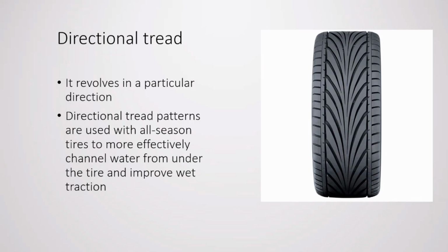Then we can experience more vibrations and jerking, because the tread pattern is designed based on the rotational direction. Especially, it will lose traction once we have some sort of wet condition. If there are wet conditions, then the traction will be drastically reduced, right? So we need to ensure that the rotation direction of the tires is correct, right?